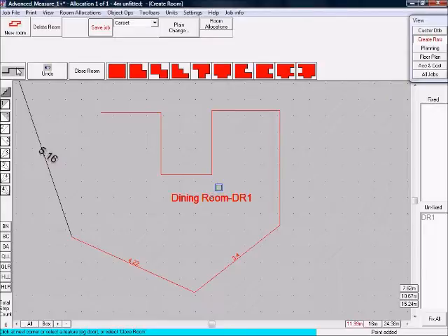The straight or diagonal button should be used where there are several diagonal walls in a row, or the diagonal slope is shallow. If there is just a single diagonal at about 45 degrees, then use the Move Offline facility we saw earlier. You will notice this time that the first and last lines haven't crossed. This is fine. Just click on the Close button on the toolbar to close the space.